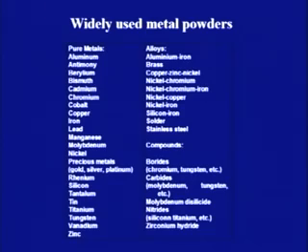Now, this may not be too clear, but just to name a few metal powders. The metal powders can be made up of pure metals, alloys, or compounds. So, we can get powdered metals of aluminum, antimony, bismuth, cobalt, lead, tantalum, titanium, vanadium. Then we can make metal powders of certain alloys also, like aluminum iron alloy, brass, nickel copper, nickel iron, solder, stainless steel. All these alloys can be made into a metal powdered form.